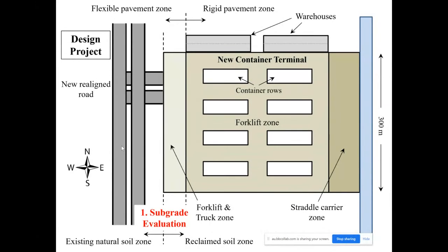So you remember soil mechanics, applied geotech, they will help you in this part. After subgrade evaluation, the second part is to determine the design traffic. You need to predict what the traffic is for the access road during the design life. This design life can be 30 years, 40 years, or other values.